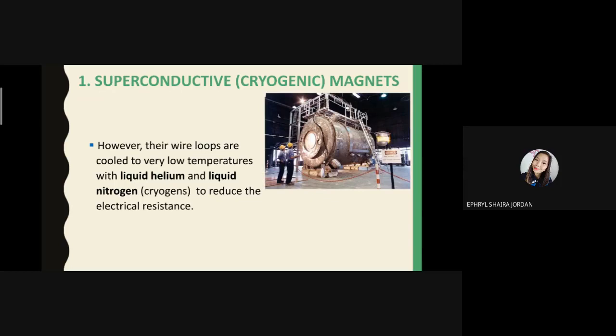To accommodate a human for imaging, the bore of a superconductive MRI could typically measure 55 to 70 centimeters in diameter. If you make an electromagnet that is that big, it really requires multiple cylinders of wire.